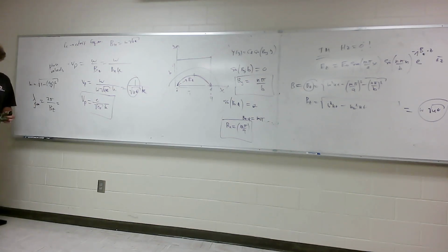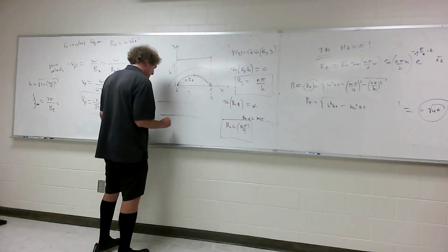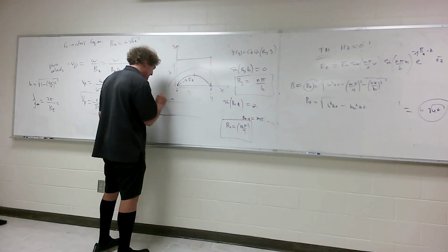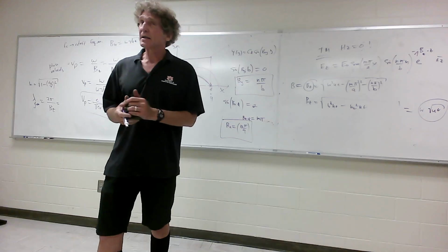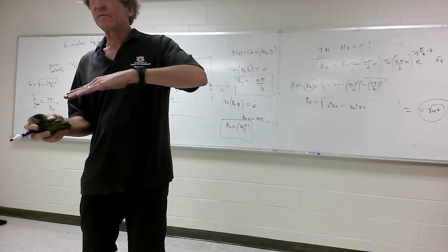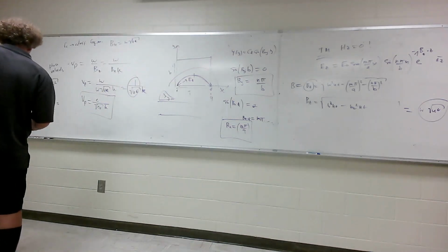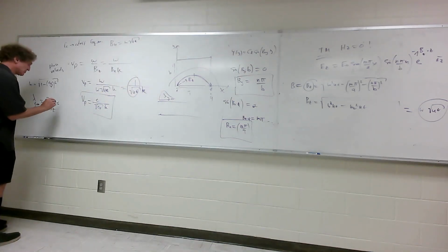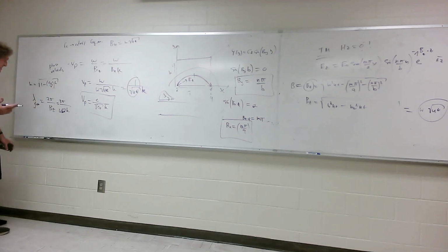And what that means is if I was looking at this thing in this direction, we're finding the wavelength down here. Now the wavelength in the guide goes to infinity at cutoff. The wave literally bounces top plate, bottom plate, top plate, bottom plate. Nothing propagates. So if you look at this, that's 2 pi over beta unguided, omega square root of mu epsilon here, and then times k. Well, k goes to 0, so this goes to infinity at cutoff.